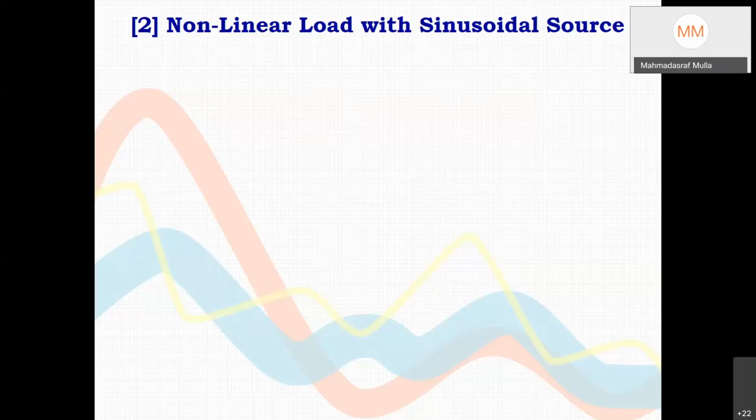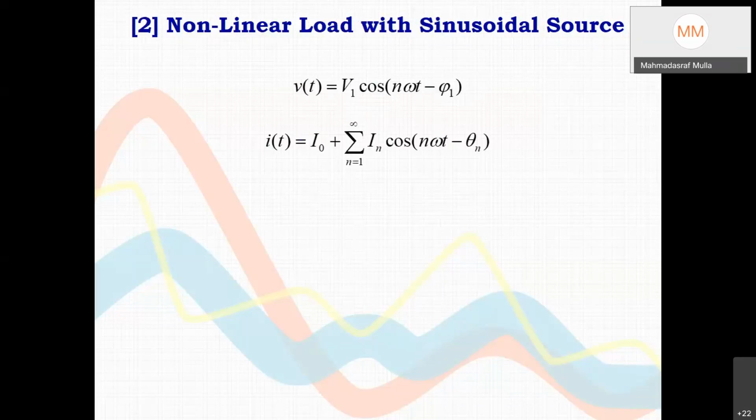Another major possibility is grid voltage is sine, but we are connecting power electronics load. So power electronics load like half wave rectifier will draw DC current also. Full wave rectifier will draw non-sine current. So different frequency AC current via Fourier series, it can be represented.